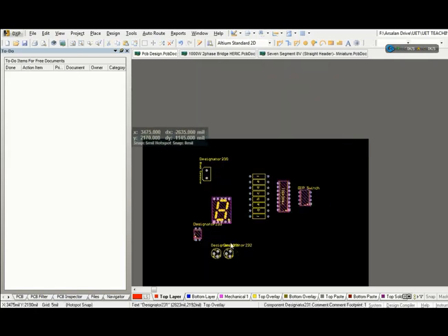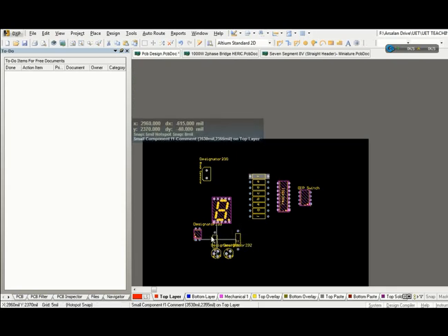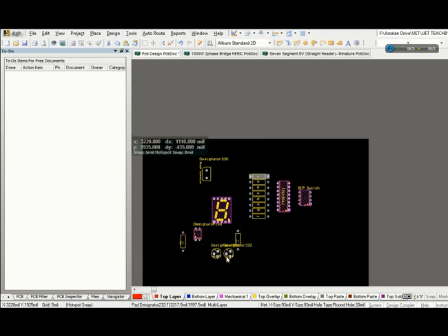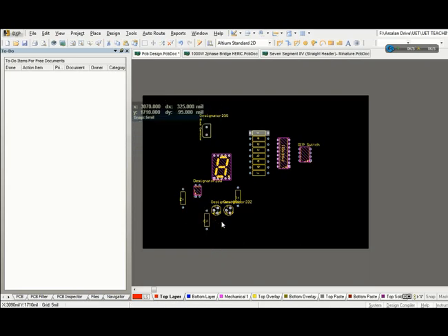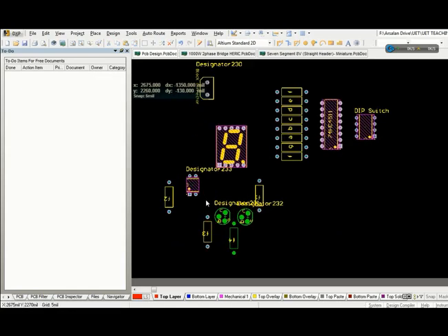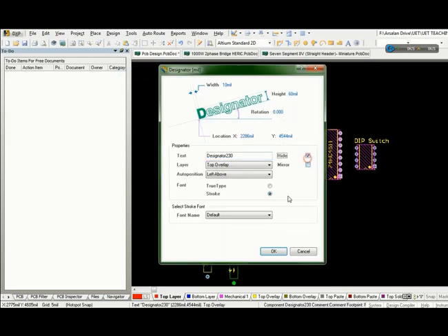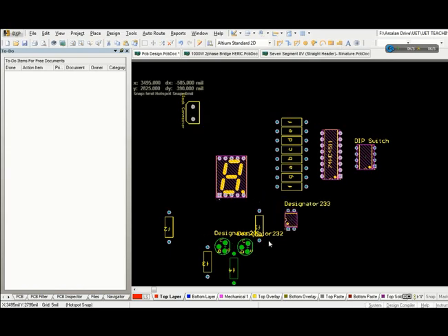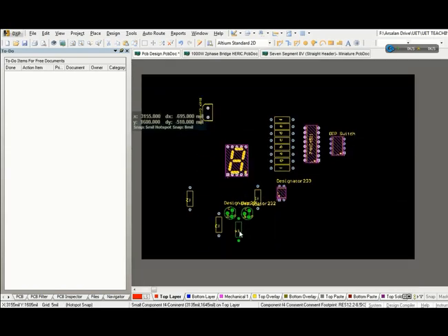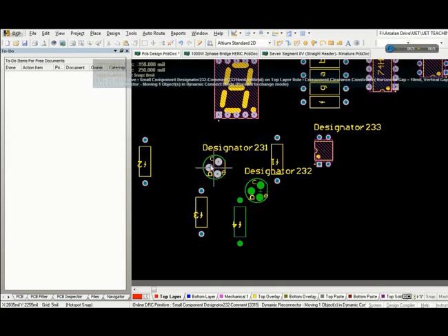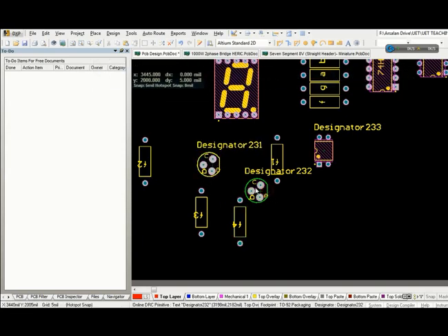Now you can see I have used a 4-bit dip switch over here, and that is one, and you are now using these resistances for the transistors over there, and then I'm going to attach. You can see now how the placement is, these two resistances which I have just placed beside the transistors, they are close to the base pin. So you can see they are the base resistors. On the data sheet, or the circuit diagram which I have given you on the website also, you can see now I am placing them.